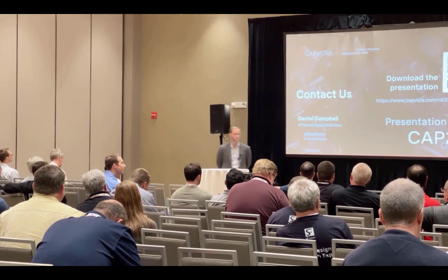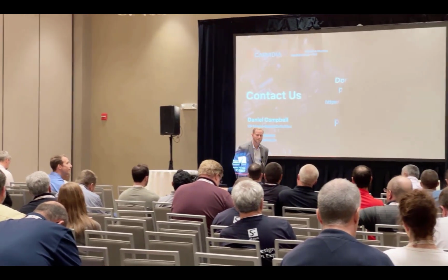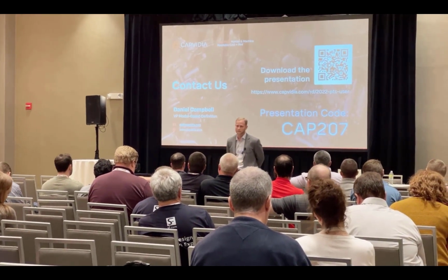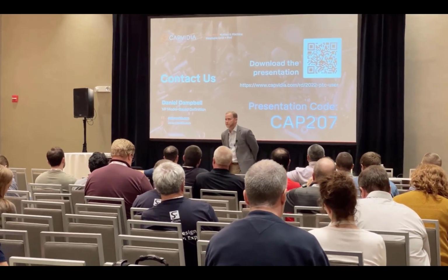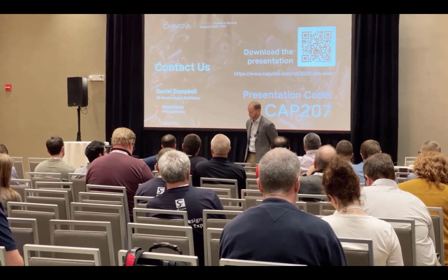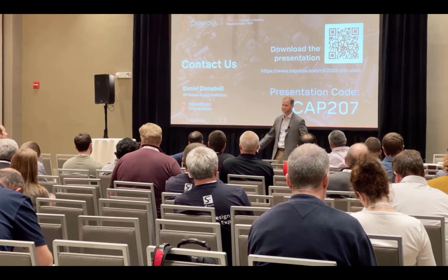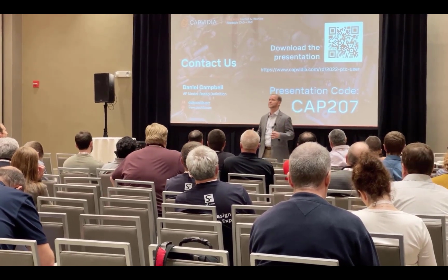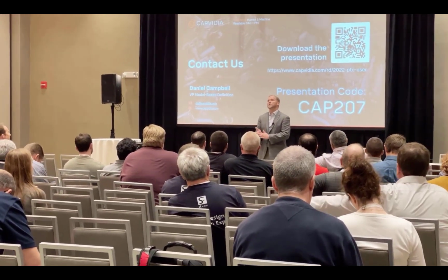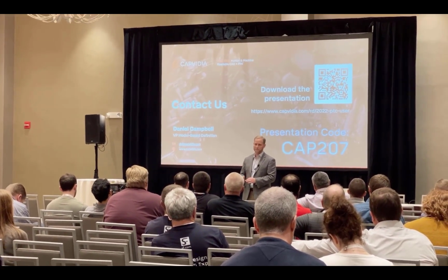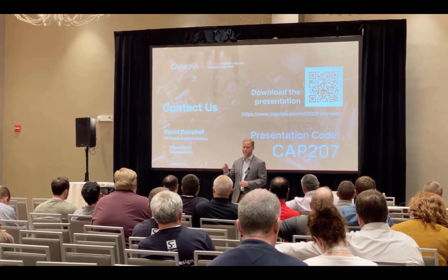How are the QIF files serialized or mediated between as-designed and as-built? So the question is, in general, how do you manage QIF files? Typically, you'll have a QIF MBD model that will be stored in Windchill and associated with your part.